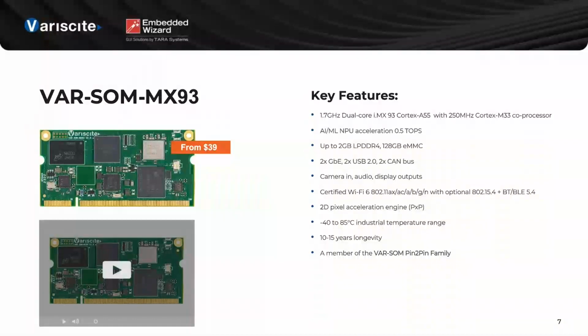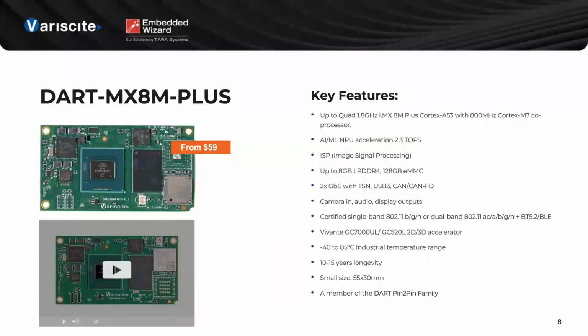Also, this SOM is part of a pin-to-pin family, while a different pin-to-pin family introduced the DART-MX8M Plus, which is a Cortex-A53 quad-core with a Cortex-M7, another NPU able to reach 2.3 TOPS, image signal processing, and much more RAM, available up to 8 gigabytes, with the same amount of eMMC, 128 gigabytes, 2 Ethernet, USB 3, and CAN FD.